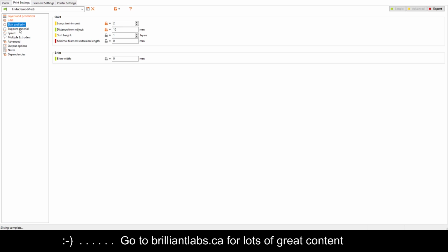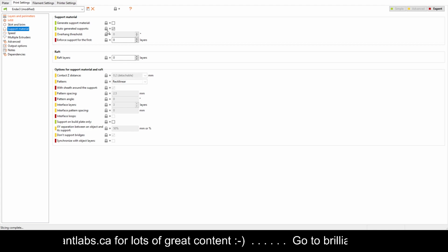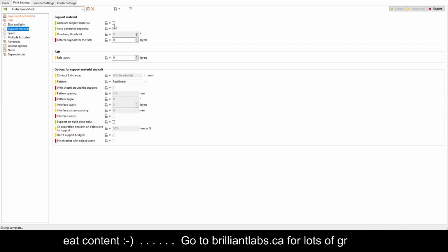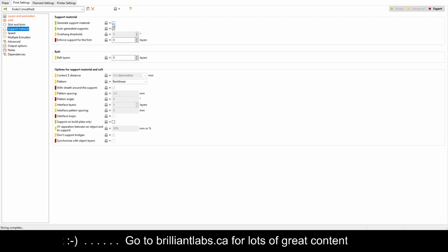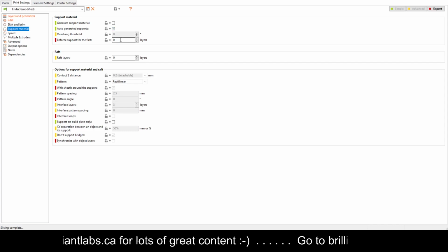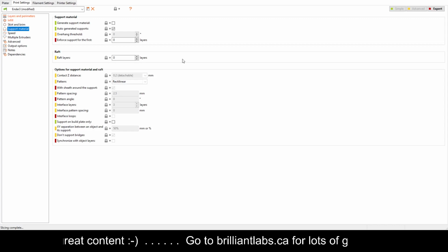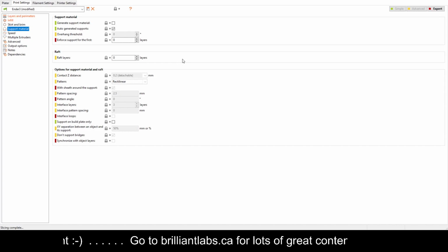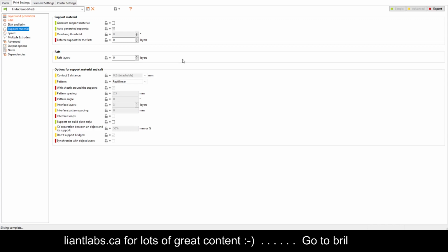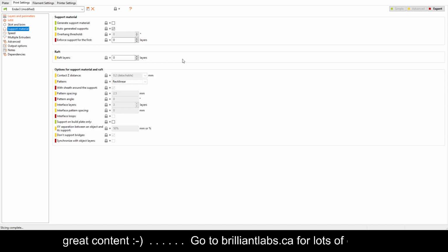All right, let's go to support material. If I thought that piece I mentioned earlier was a problem printing, I could check generate support material, and what would happen then is that material would get printed underneath that piece to support it while it's printing. Now, I printed this one, the one I showed you, earlier, and it printed fine without supports. And because it's not as important aesthetically what it looks like, I just left it that way without having to put the material in there.